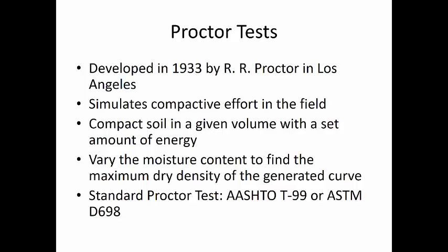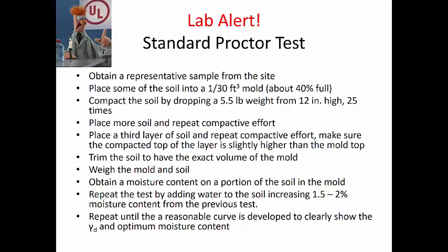The standard Proctor test, or at the time just the Proctor test, was developed to allow engineers and technicians to follow a specific standard, so everybody was speaking the same language, and we knew that the soil can be compacted at a specific rate and energy level. So the standard Proctor test is AASHTO T99 or ASTM D698. Those are basically the same exact test methods, depending on if you're utilizing them for highway projects or any other project that requires densification and field compaction.